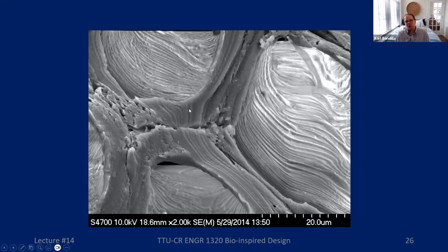right? So if a fracture comes to a boundary, it will kind of go along the boundary instead of going across the boundary. And there's all kinds of reasons for it, free energy at surfaces and all that kind of stuff. But that means that if for some reason this tube here gets a crack and starts to fracture, it doesn't just fracture to the next one and the next one and the next one, the whole thing just collapses. No, it actually stops there, right? So only one of them gets destroyed and the rest can stay the same.